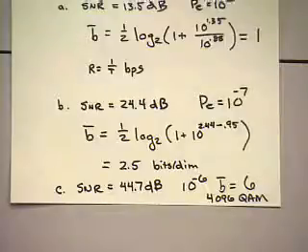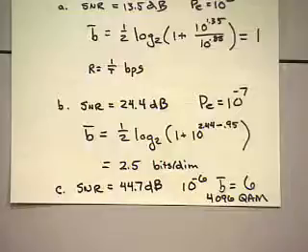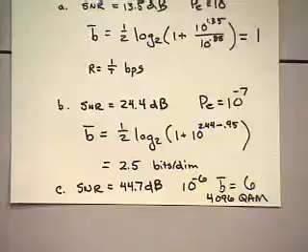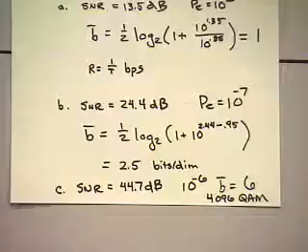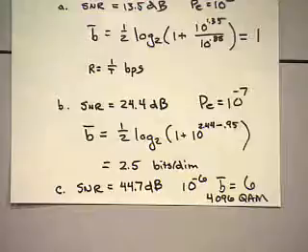The actual DSL modems are the highest efficiency systems, and they get all the way up to 15 bits per symbol, or 7.5 bits per dimension. They actually use multiple QAM signals across a 1 megahertz band, and if you have a reasonably short telephone line, which a number of people do, you'll see that system capping out at 15 bits per QAM signal. Basically it works out to be about a 32,000 cross constellation that's used in those modems when they can transmit the 15 bits per dimension.